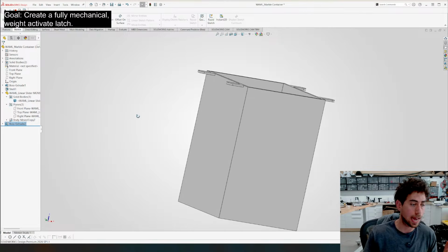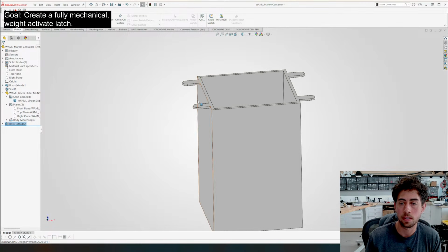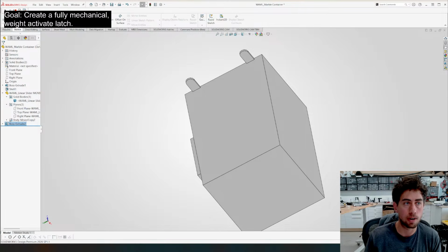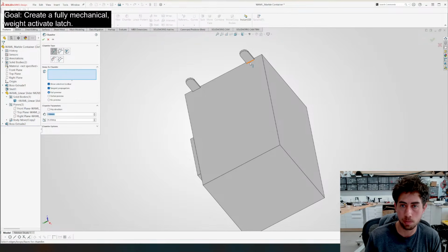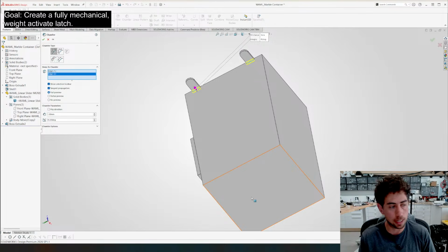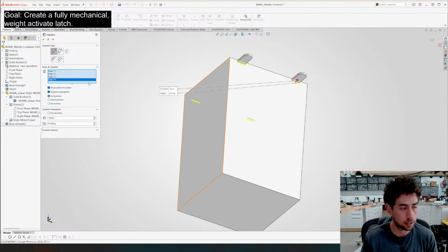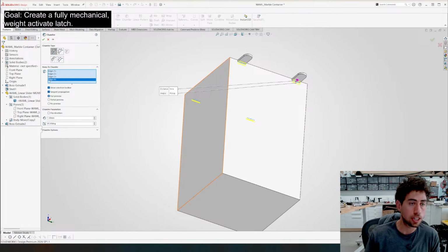So this is where right now I'm thinking about how to design for printing. That's why I'm doing it this way, and then I'm going to put a chamfer on this. This right here is going to be the bottom, on the bed of the printer. And then this is going to be on the top, but these can be an overhang. So the outer shell is going to drop with that inner moving thing. It will start to make sense really soon, I think.